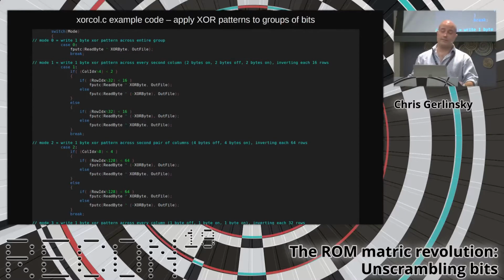So looking at the patterns, in this case, I did have some plain text available from some of these chips. These ST19 smart cards are used in a variety of systems, and some of them have been exploited in other ways, for example, glitching to extract code. So for some versions of these chips, I had pieces of plain text code, and by comparing the plain text code to these visual patterns, I wrote a program that just reverses the visual patterns that I see. I didn't actually fundamentally understand the process that they were using for the scramble.